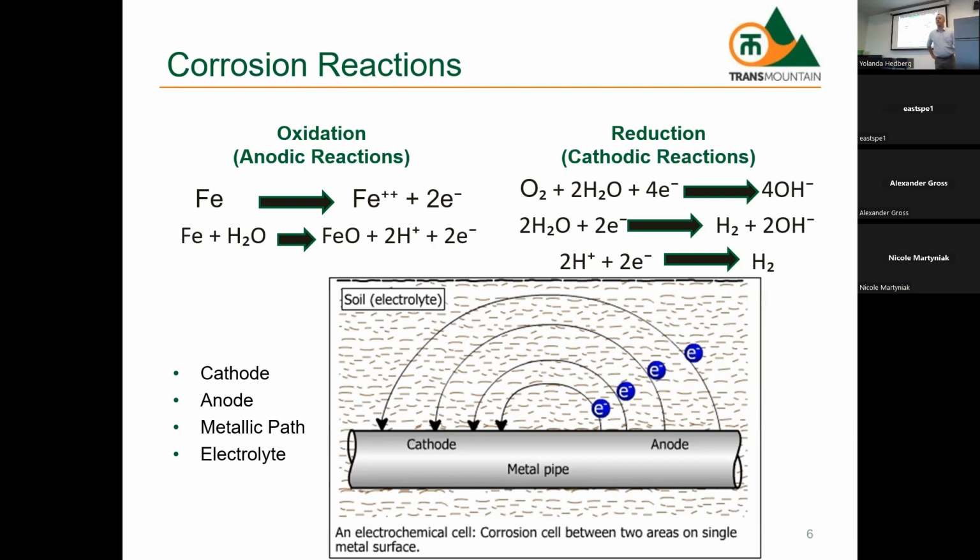That's a good point, because if we're strictly talking galvanic, the metallic path is when they're touching because they're conductive. But if they're close and we have a conductive medium like water or salt water that's highly conductive, and they're close enough, the connection goes through that conductive medium. But the way to combat that is to coat, to put some other dielectric barrier between the two.